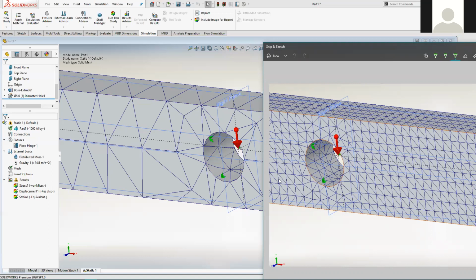And the reason that it would be pointless, that I haven't stated yet, is just that the calculations on the right-hand side mesh here will take significantly longer than the calculations on the mesh on the left. So that's the trade-off. Calculation time is what you're trying to minimize. And obviously the reason for that is that it does calculations at every little node point where triangles meet, and there's a lot more of them on the right. So it's doing the same calculations, just a greater quantity of them, to give us a more detailed rainbow plot when we come to the stress plot.